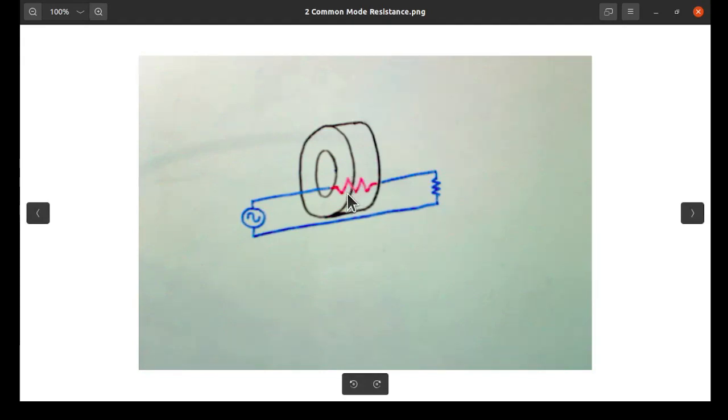And in this regard, the loop goes through and outside the core. This is your first primary lesson in not only common mode but balun construction. This is going to turn into a very simple one-to-one balun in very short time.